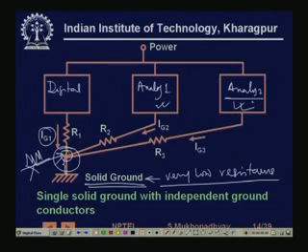So the whole basic idea is that, first of all, these ground resistances must be kept as small as possible, and secondly they should be connected separately and then connected to a solid ground. This is one of the reasons why you see all the time that ground planes use thick conductors on the PCB layout.